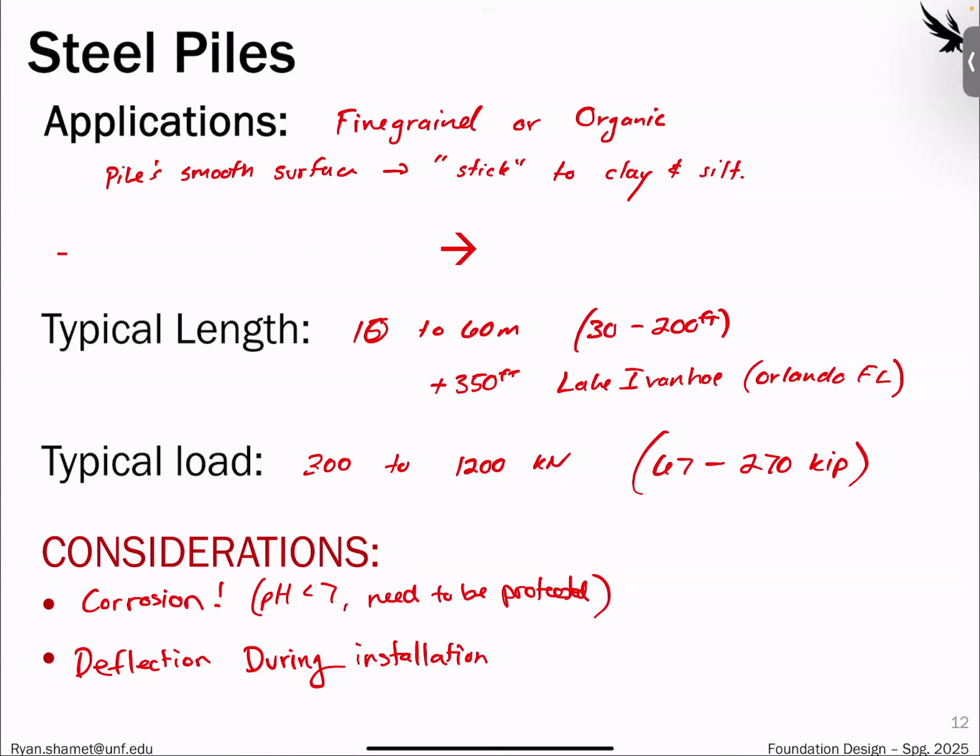And eventually you get to a point, it's almost like a nail that you're hitting into the ground or into some dense wood. Eventually, you get to this point where it's so bent, you're just like, oh crap, I can't use this nail. And you just lose it. You either hit the nail down and can't pull it out, or you scrap the nail. And that actually had to happen. We had to scrap a few piles because they were too bent and you couldn't get the capacity you needed out of them. So next time you drive over I-4, know there are hidden piles in the ground.